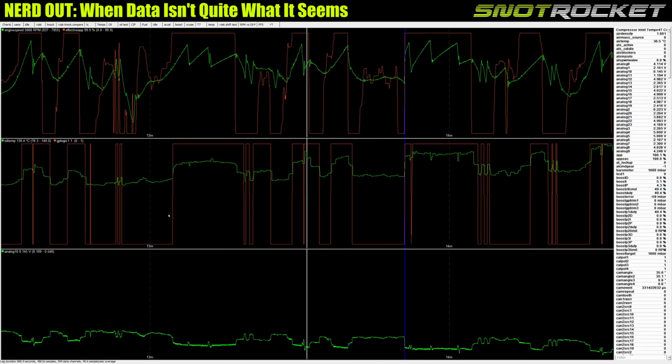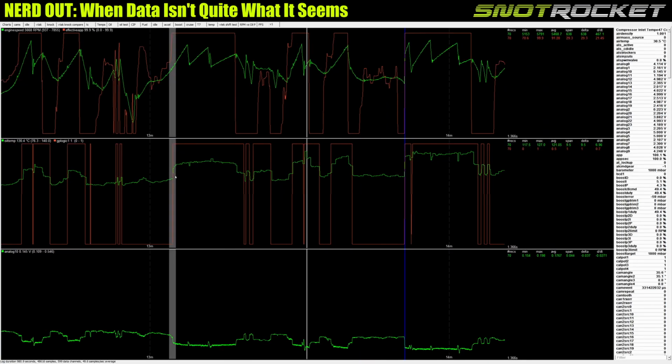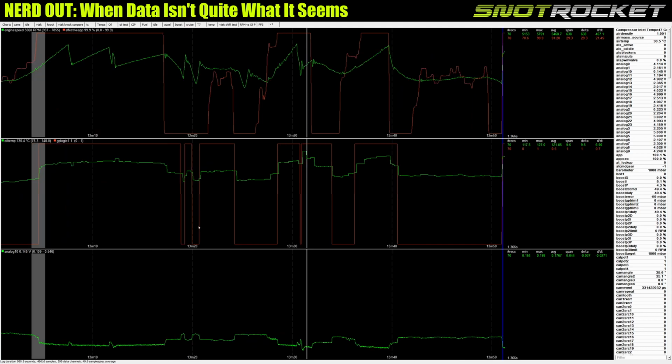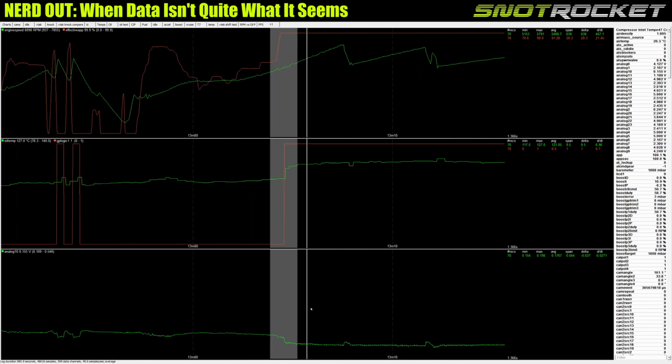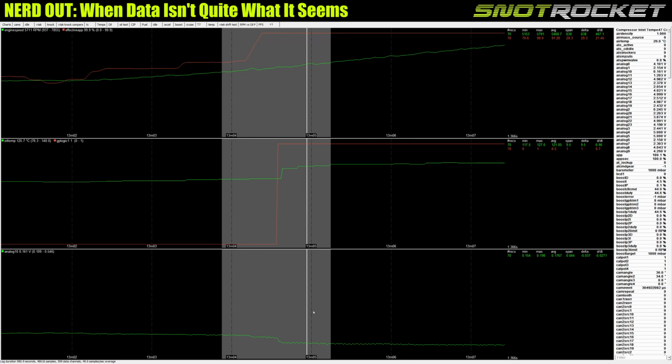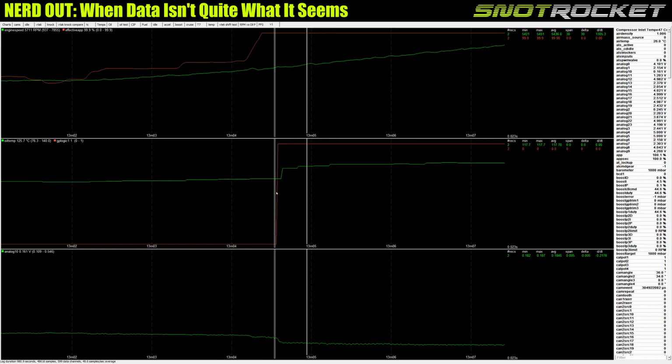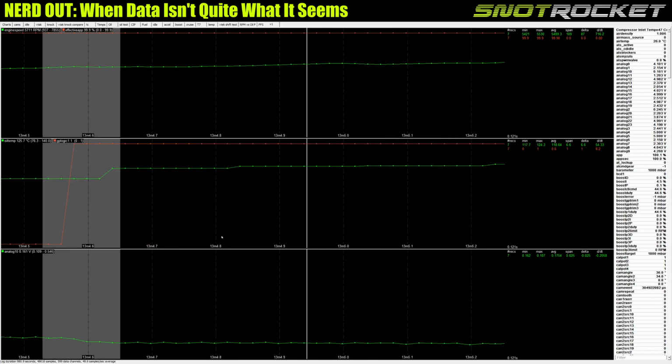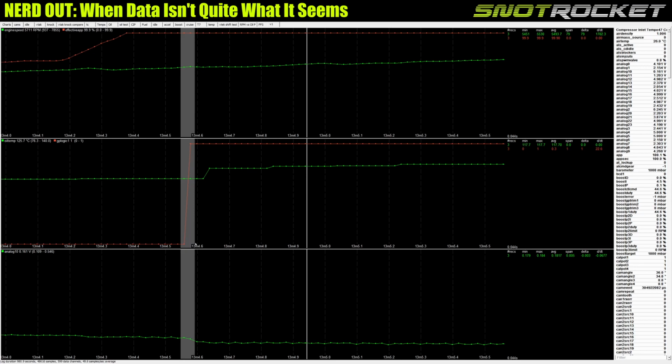And if we go to an area like here where we know there's an issue, I'll zoom in a bit, you can see down here there's a step. When that switch is here, there's a drop in the voltage, which is correct because the voltage changes, the temperature appears to change. But what we see here, just from the point of that VTEC switching, right?